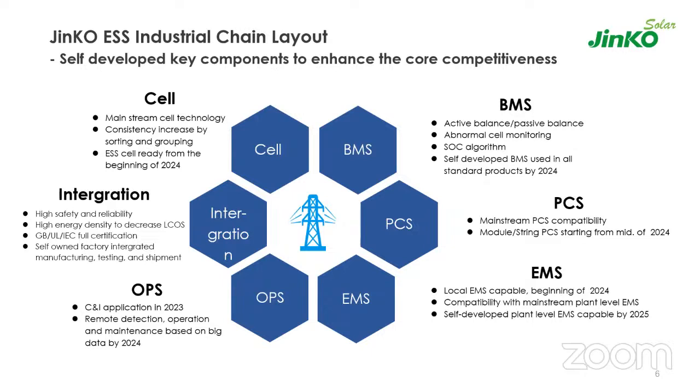Specific to C&I markets, it's just standing at 100 ampere hour or even close to 280 Ah. And utility scale cells stand between 280 Ah to 300 Ah, or even 320 Ah is expected. These cells are stacked up in a module, then module to pack to rack, and that's how it is considered within the entire container.